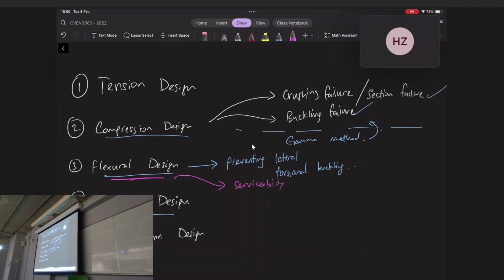Okay? What serviceability covers is how much this thing will deflect. Okay, so for example, if you've got a floor and there's a beam running under it, if I step on this floor, maybe the beam is strong enough to hold me up, right? But it could deflect a lot, right? So my job here is to figure out not only what happens in the ultimate case, but what happens in an everyday situation, right? In an everyday situation with people walking on it all the time, yeah, it might not break, but it might deflect, right? Like an elastic deflection, and we need to prevent that, okay?